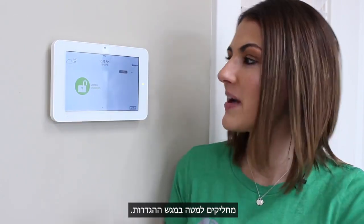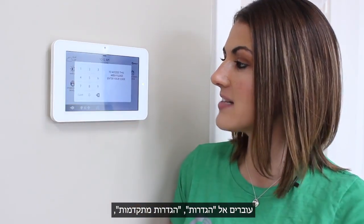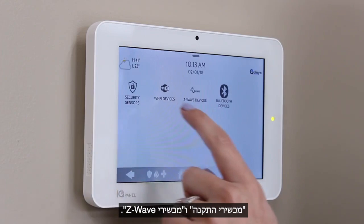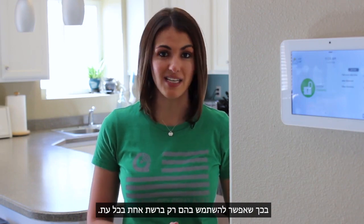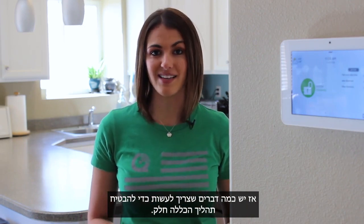To include a Z-Wave or Z-Wave Plus device, start by swiping down on your settings tray, go to Settings, Advanced Settings, type in your installer code, Installation, Devices, and Z-Wave devices. Z-Wave devices are unique in that they can only be used in a single network at a time, so there's a couple things you should do to ensure a smooth inclusion process.